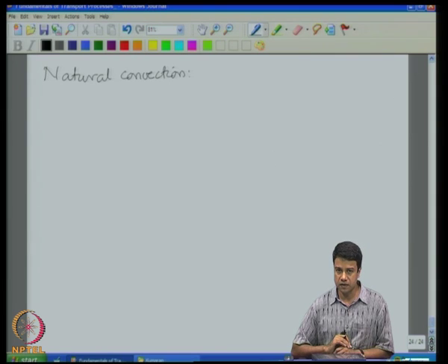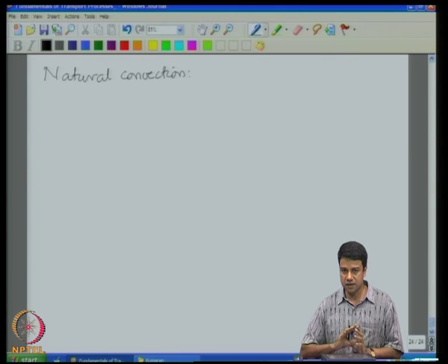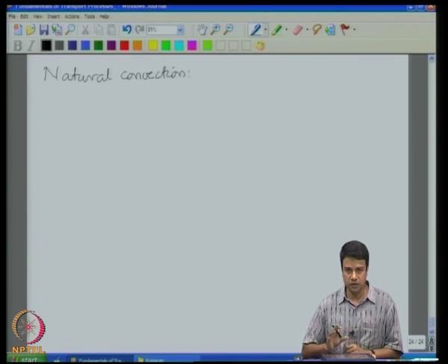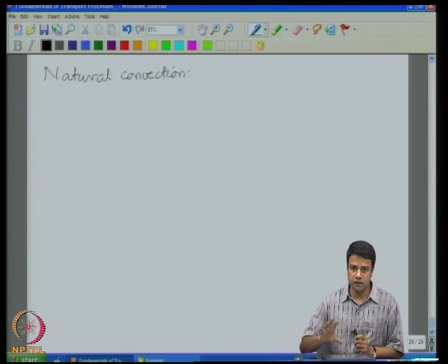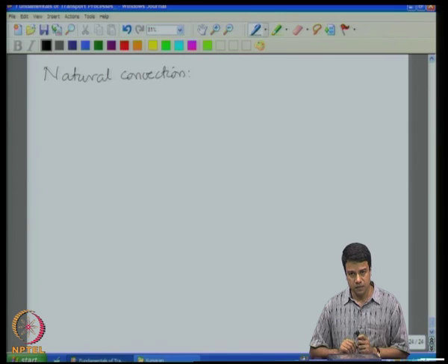Forced convection heat transfer is where the velocity field is basically determined by the external action, by the pumping, for example, of a fluid through a tube or around an object, and that velocity field is what convects the heat away from that object. Natural convection is the other way. The surface is heated, and because the fluid is hot near the surface, the density is lower, and because the density is lower, it tends to rise because of buoyancy effects. So, the velocity field itself is created by the heating of the surface itself, and in that sense natural convection is a little more complicated.